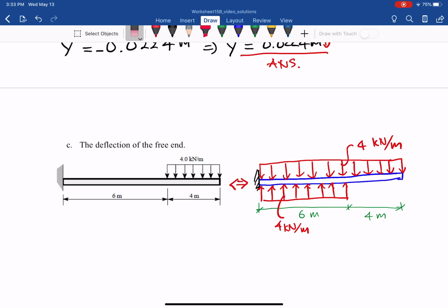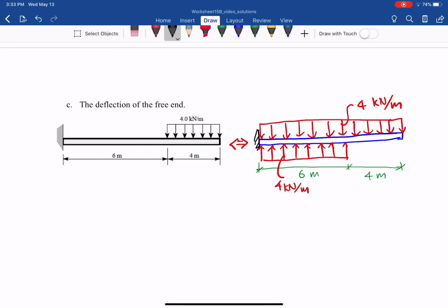So with that, it's like if you have no money, in this case the 6 meter, right? It's equivalent to you receive $10 and someone takes out immediately $10. So you still have nothing in the pocket. Exactly the same in this case. So with that, how can I make it equivalent, and then as you can see, the problem becomes what? The cantilever for the whole 10 meter.